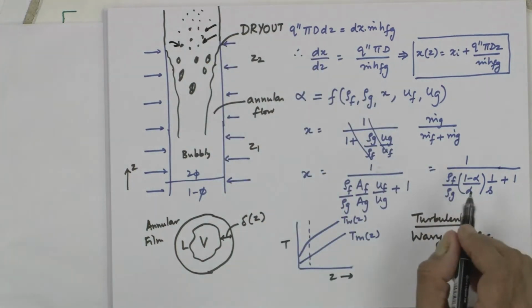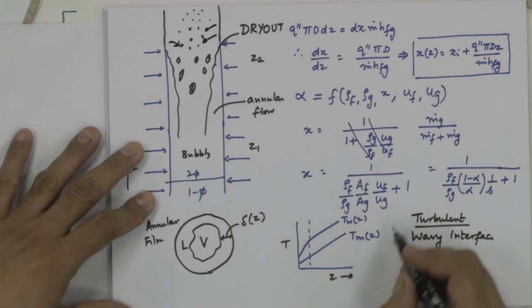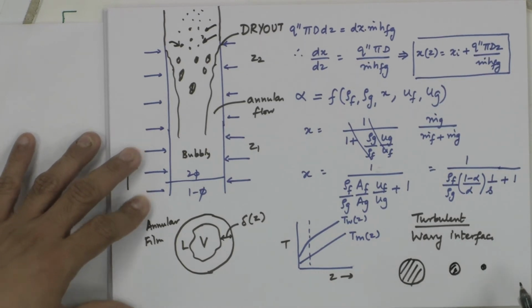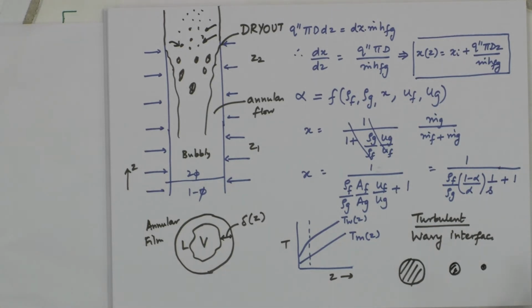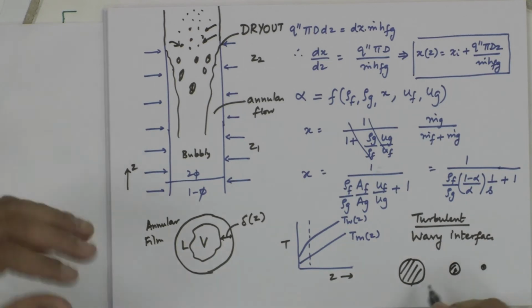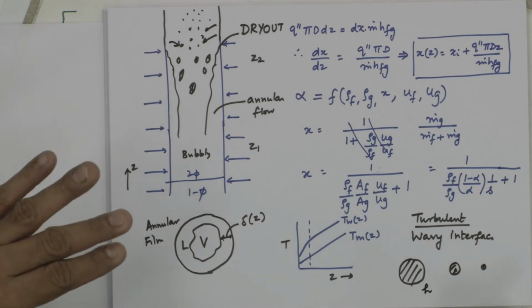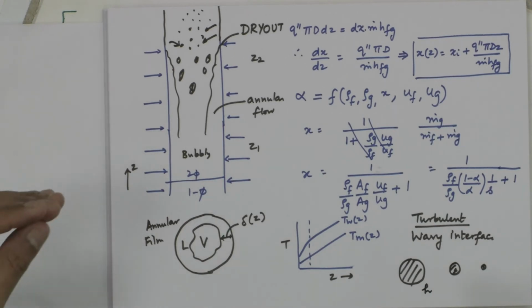So, when there is a liquid, the heat transfer coefficient is good. Evaporation, or if this is a large droplet, when it evaporates it becomes a smaller droplet. Evaporation is a surface phenomenon. 4 pi r square is the surface area of a sphere. So, there is a nice surface area through which evaporation occurs. So, H can be reasonably good in case of a dry out, where because of these droplets which are present, though the droplet size will decrease, you have a sink for the heat.